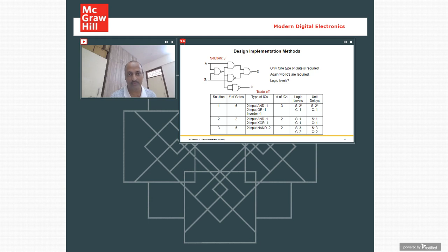So we can do it using simply De Morgan's application, and we know we can convert any circuit into NAND technology. Okay. So if you look at the output expression for sum, there are three stages. First stage is NAND of A and B together. Then the second stage, output of the first stage is inverted, and the third stage. So in this case also, there are three time units required for the sum to be made available at the output, whereas carry output is available immediately after the first time unit.